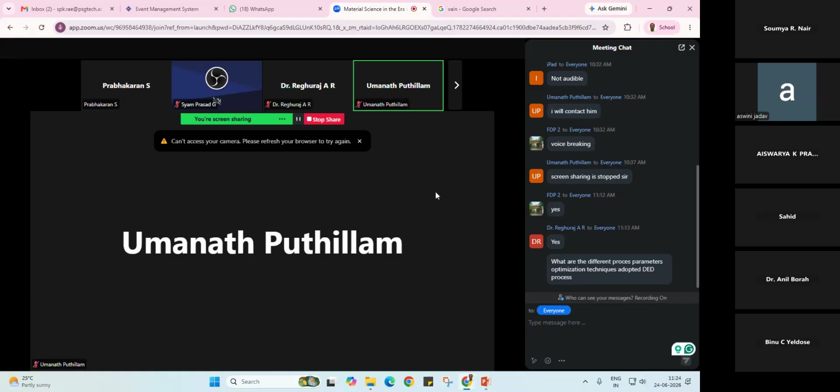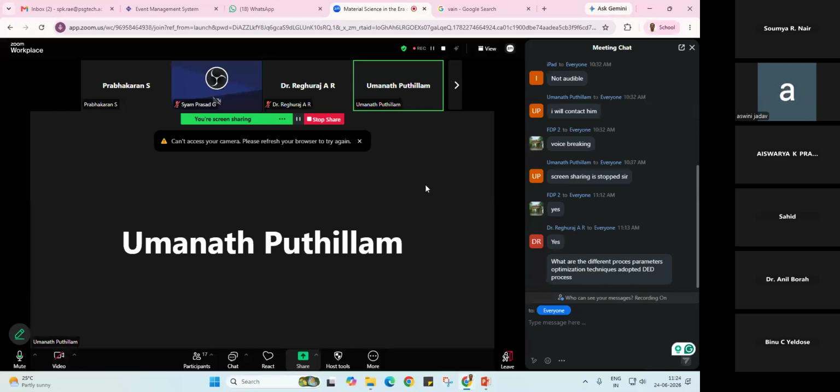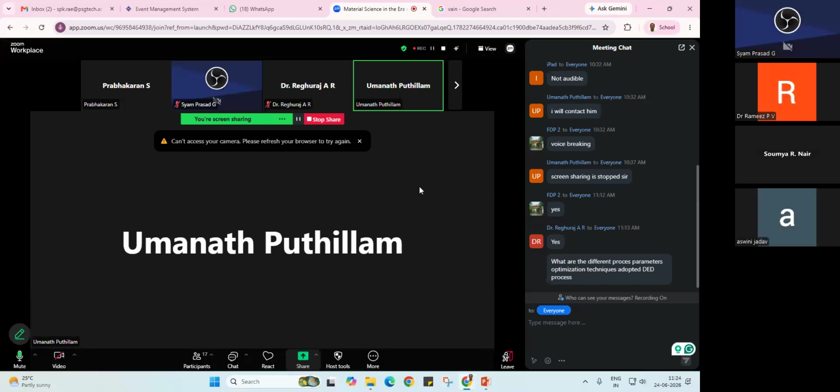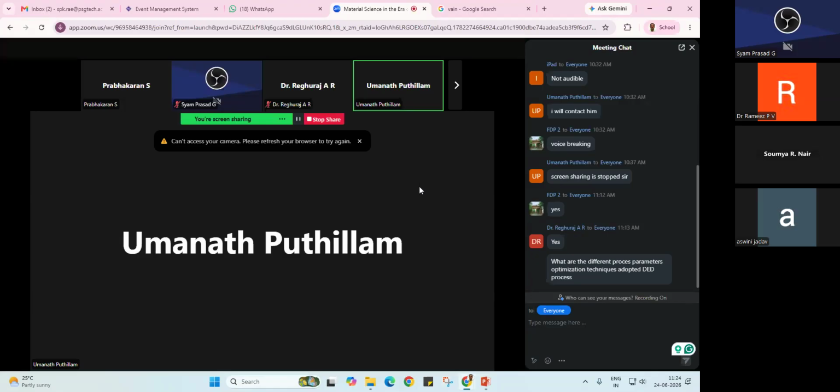Sir, one question from the chat box. What are the different process parameter optimization techniques adopted? There are several methods available, sir. Starting from Taguchi, ANN, particle swarm optimization, anything you can use. Mostly research scholars are using the Taguchi method. Some people are using neural network methods. Some people are using machine learning techniques to optimize the process parameters. It depends upon the user. Every technique has pros and cons.